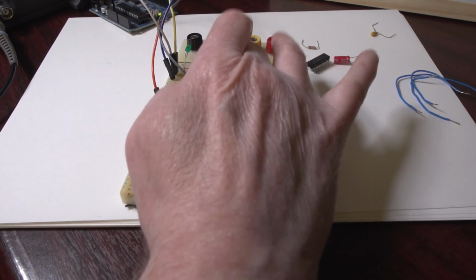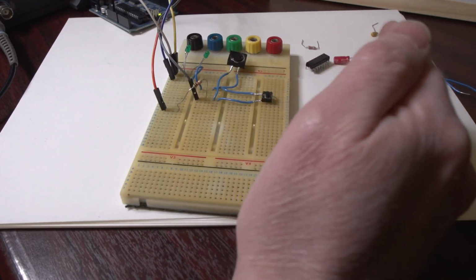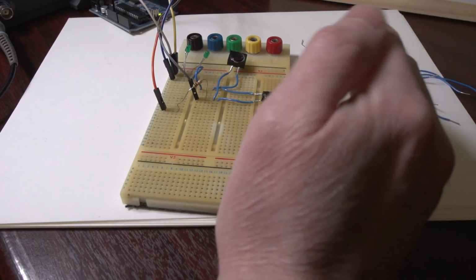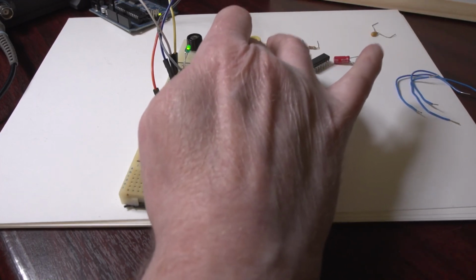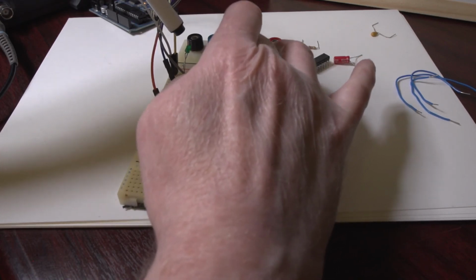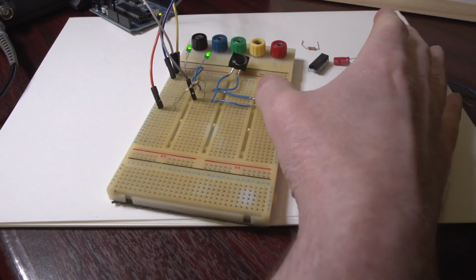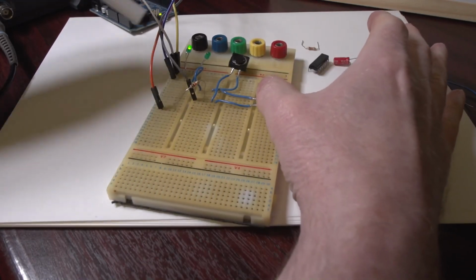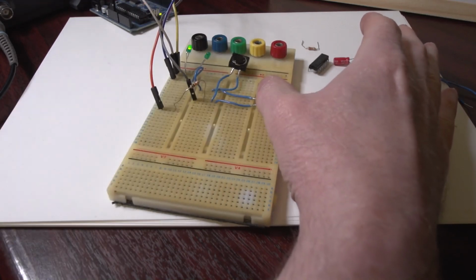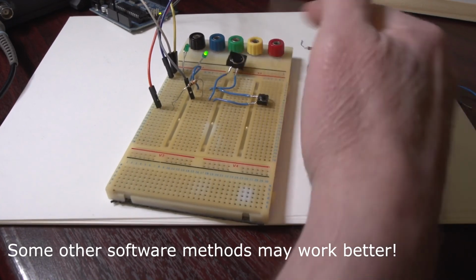So yeah. The other problem is you can't press it very fast, because remember we've got a 200 millisecond check to see whether it's a real press or not. If you press it fast, you'll notice this is flashing much slower than what I'm actually pressing. It's not reacting to my speed at all. There's a limit to how fast you can actually press the button. You can see that. It's flashing much slower than what I'm actually pressing. So there really is an actual limit to how fast you can press the button.